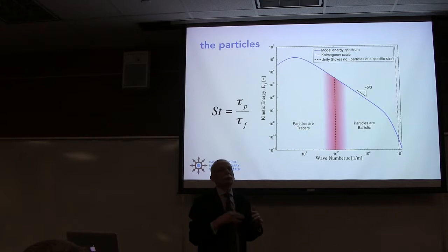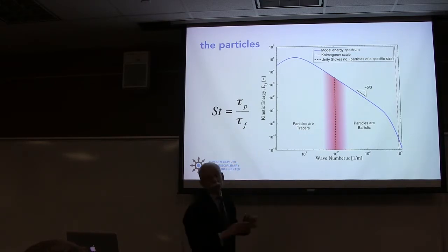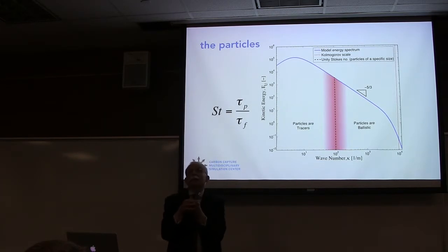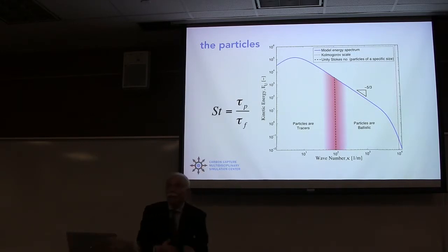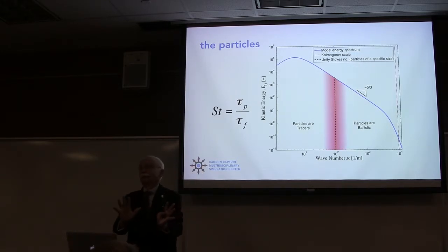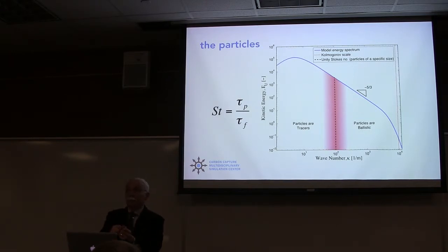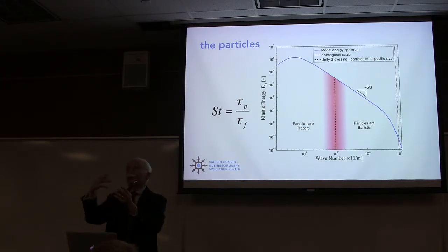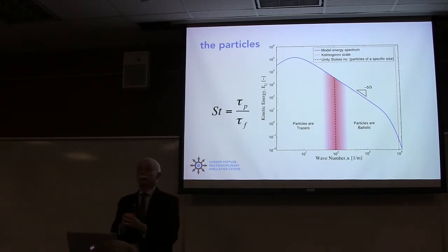And this is a power spectrum that you probably do if you've done in your electrical engineering classes or otherwise. But we like to think of the kinetic energy of those eddies and recognize that there's a hierarchy of eddies, and that they're dissipating that energy. I'm positive that you learned that this momentum balance is just an energy balance that's going on here. As much energy as is put in the system, we have to dissipate in the system. And that's why we create this turbulence, so that energy can be dissipated, so that we can have an energy balance in this overall system.